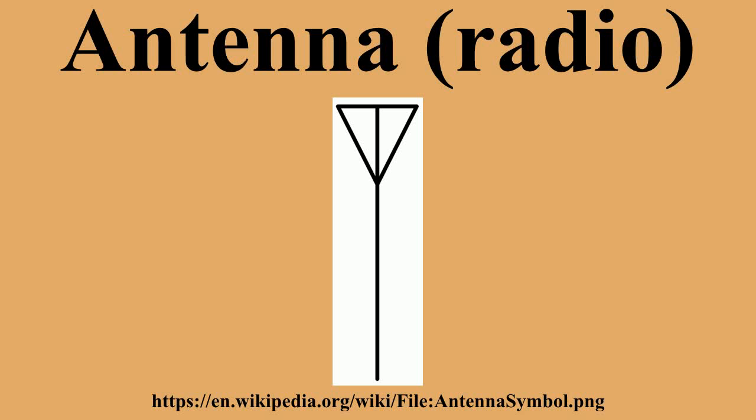Both the vertical and dipole antennas are simple in construction and relatively inexpensive. The dipole antenna, which is the basis for most antenna designs, is a balanced component, with equal but opposite voltages and currents applied at its two terminals through a balanced transmission line. The vertical antenna, on the other hand, is a monopole antenna. It is typically connected to the inner conductor of a coaxial transmission line. The shield of the transmission line is connected to ground. In this way, the ground plays the role of the second conductor of a dipole, thereby forming a complete circuit.